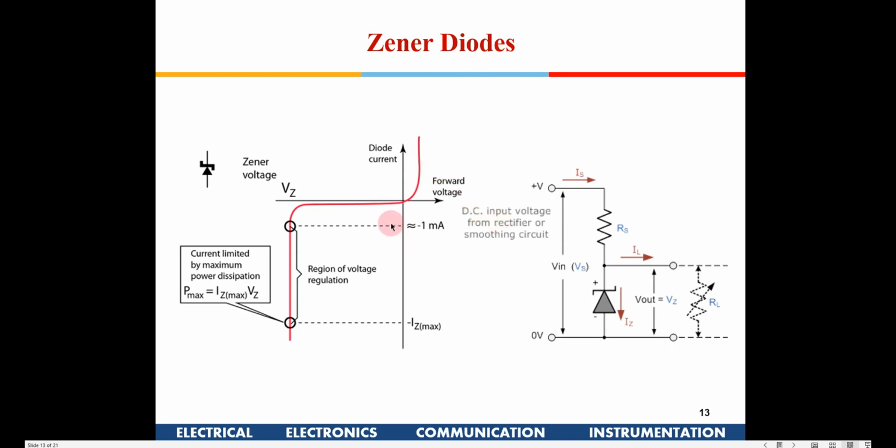Okay. Now there is something known as Zener diodes also. We will not get into too much of the mechanism of Zener diodes, but like we said, the diode breaks down when we give a certain negative voltage. The Zener diode works on avalanche breakdown or Zener breakdown, where when you give a certain negative voltage known as the Zener voltage Vz, which is the rating of the diode, the output voltage remains constant. Here, if you see the curve, the output voltage remains constant, and it can provide a range of current while maintaining the output voltage across the diode as Vz.